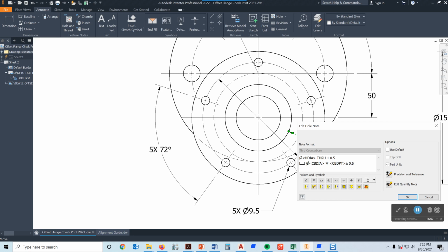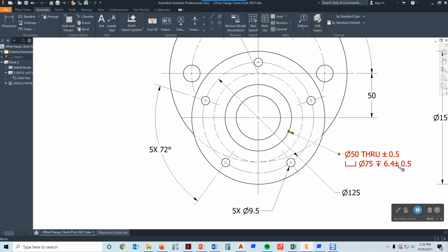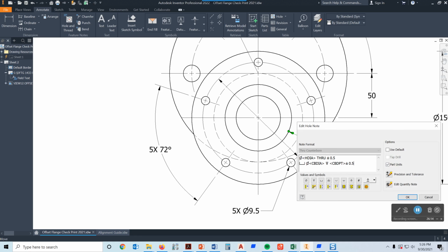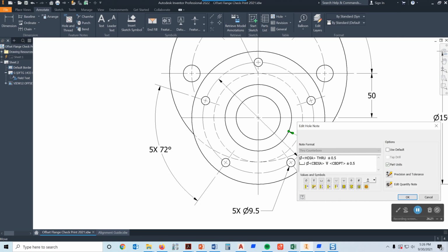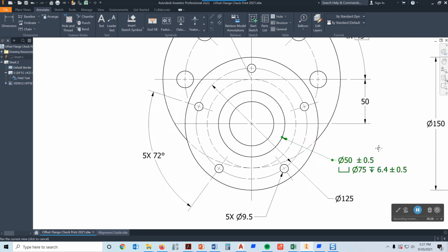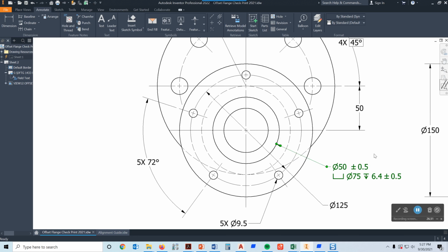That's according to the sketch that I have, these tolerances that are a little bit different than what they are everywhere else. I think I would like a space after that, maybe a space after this. Pick OK. All right, and in fact, I can take out this through. I don't need to have that in there, and pick OK. So it's looking a little bit cleaner now. So if I go through and I highlight everything that I've done now, I have just about everything in here.